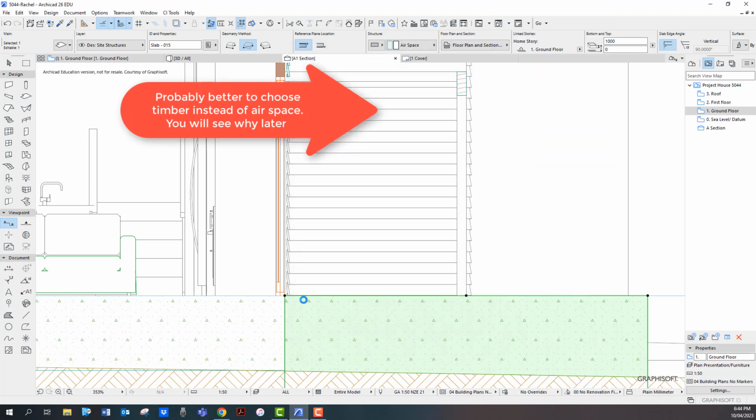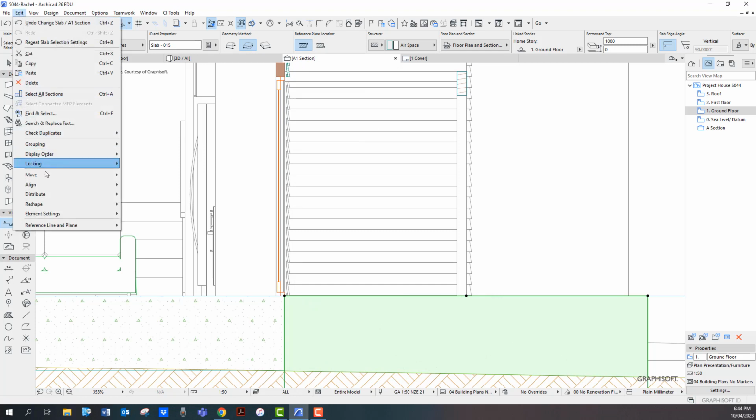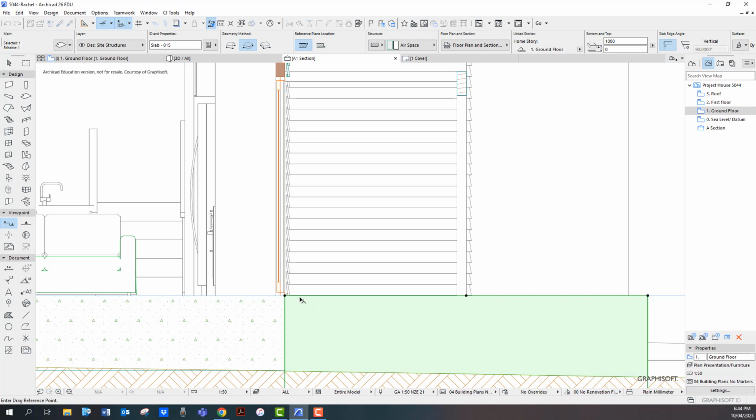And even though the deck has been drawn as level, I'm going to drag that down a bit. So I'm going to say edit, move, drag, and just say drag it down. I'm going to say Y 150 minus, and that should then take us into what we have with our 3604 and E2 AS1.